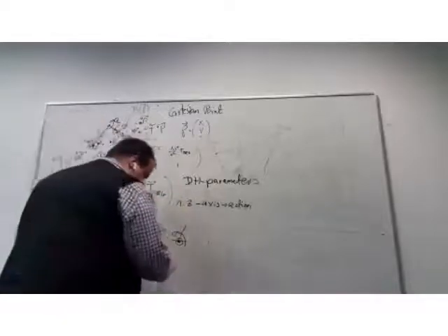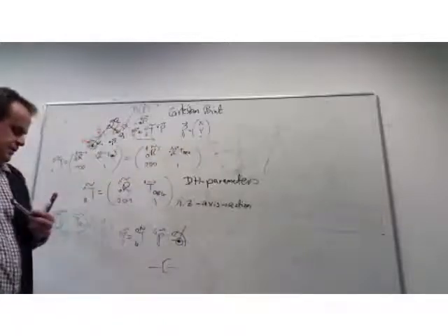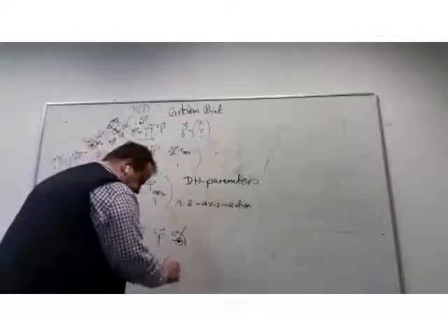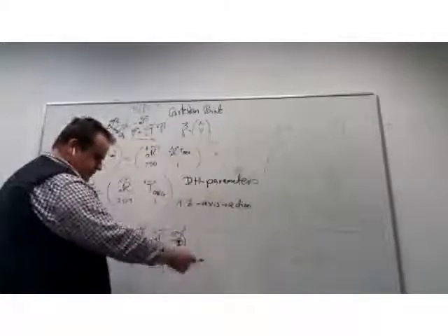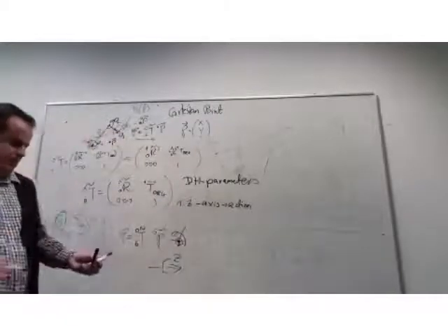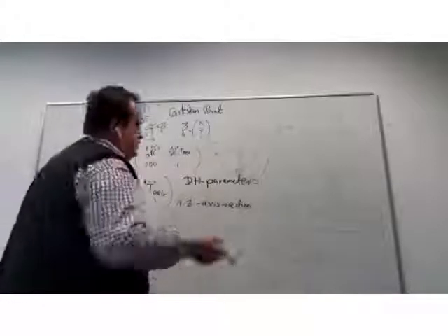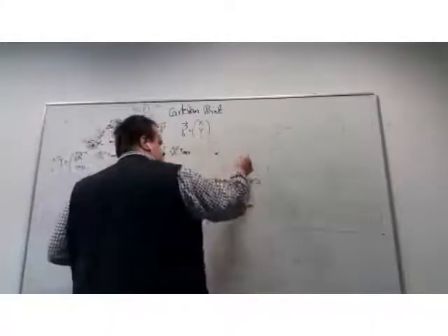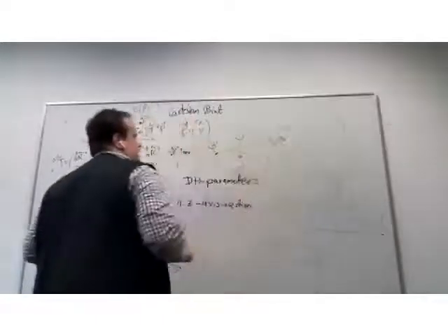If I have a linear prismatic joint, then my axis Z would be pointing out of the board here. For a linear joint, the axis would be pointing. So first I choose the axis of motion. If I have rotating vectors, there will be some rotation happening here, some rotation happening here, and some rotation happening here.